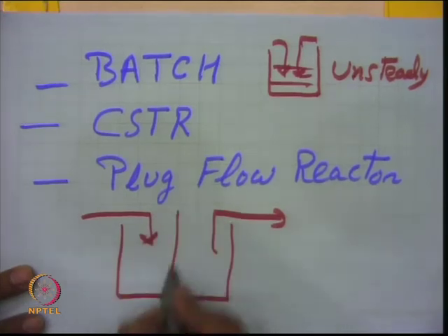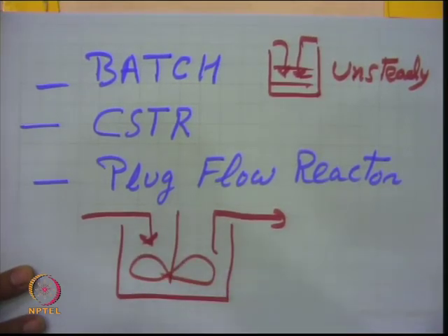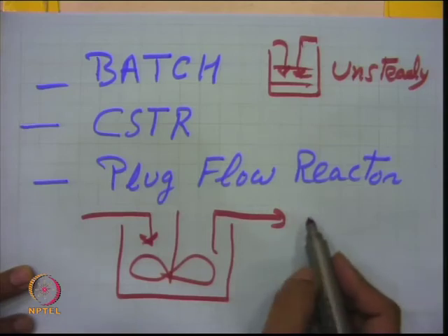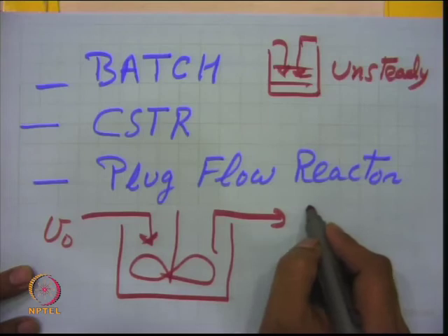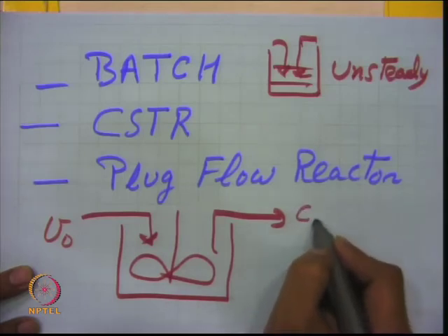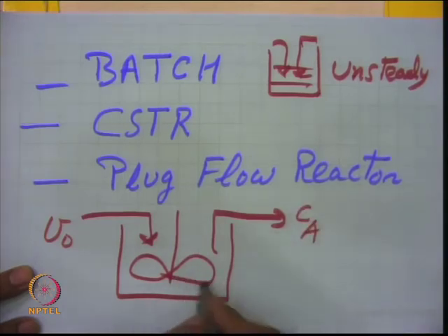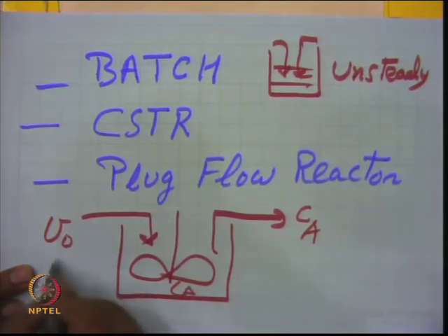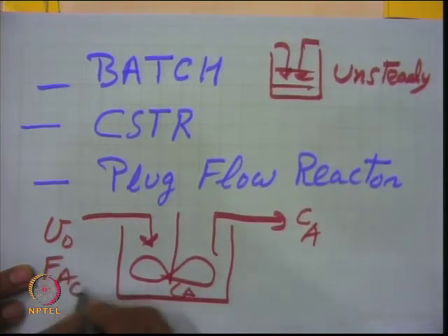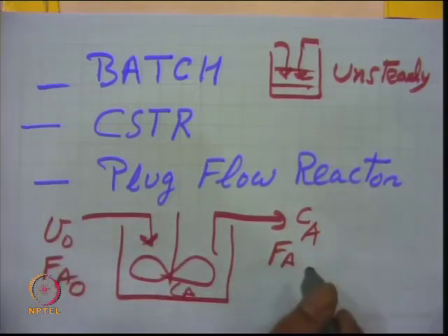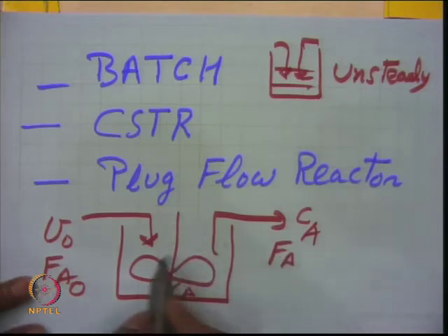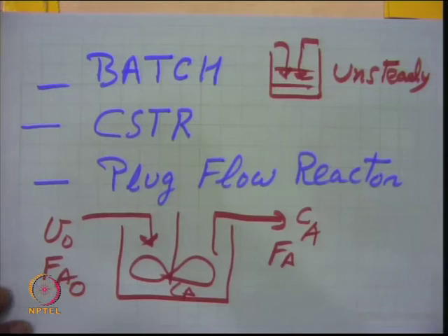But in the case of this flow reactor CSTR, a tank type reactor, you have continuous stirring here and the product is taken continuously outside. So, something is continuously flowing in and something is coming out also. So, the concentration inside the reactor and Ca here is similar, right. The moles in, Fa not inlet and outlet may be Fa. So, conversion can be calculated based on input minus output moles of the reactant species, and time is decided based on the reactor design fundamentals, that is the mass of the catalyst which is placed here.